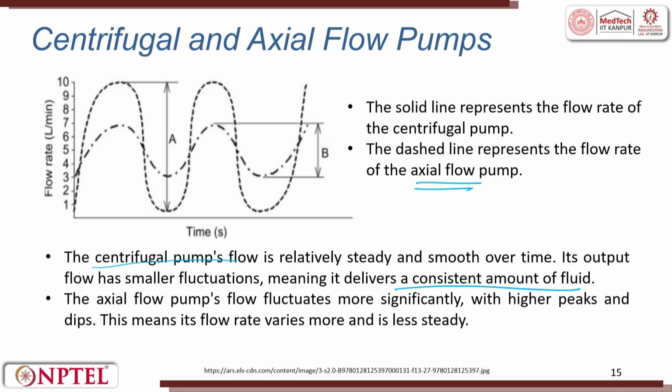In the axial pump you see a large sinusoidal wave. This large sinusoidal wave shows that there is a lot of fluctuation with respect to time. So, if you want a steady state, this pump will be attached to a container where the water is filled and then ejected. That is how it happens in water jet cutting machines, because the pressure required is very high. So, the water is pushed into an intensifier. The intensifier is a tank which amplifies, and then it finally gives a steady flow out.